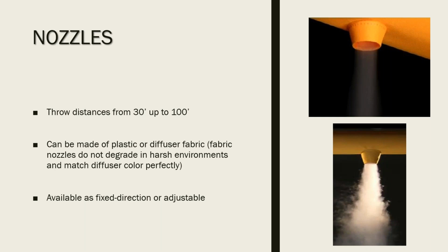They can also be made with dampers. Let's say you have 20 feet of duct. The first 5 feet, you don't need to have any air. You want to shut off air on the first 5 feet. So you can put dampers on the inside to completely block off air in the first 5 feet of the duct, and then the rest of the duct, the last 15 feet, will have air coming out of those nozzles. And of course, it will be custom designed based on static pressure and all of that. That's all required, and that's information that's given to us by the engineer.